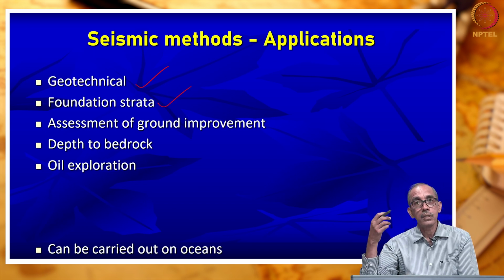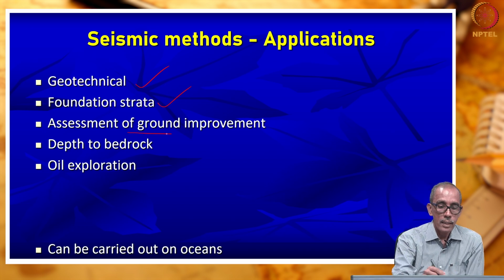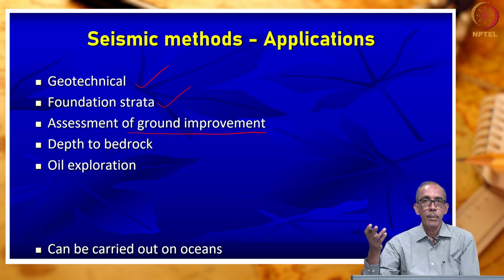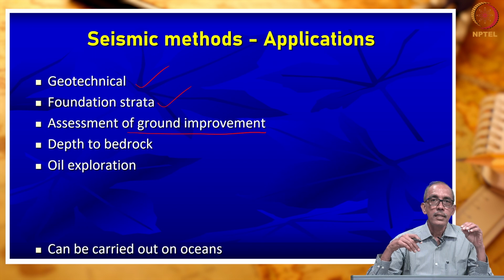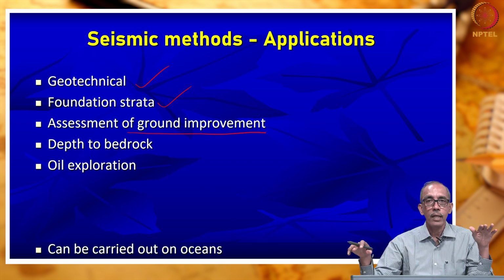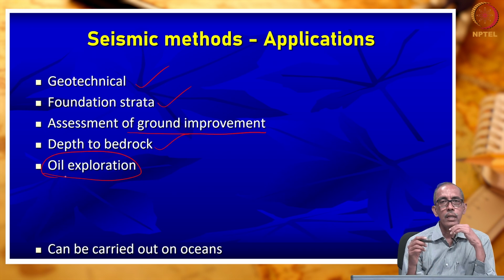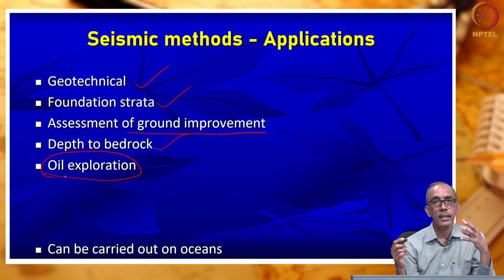Also, we have used them a few years back to understand whether the ground improvement work which we have carried out has really improved the ground by making seismic measurements, before improvement and after our ground improvement. Right? Often used to understand depth to the bedrock. This is the only tool that helps us to understand greater depths below the surface of the earth, right?